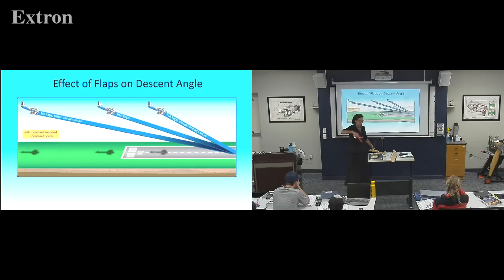You have the flaps helping slow you down, so you can clear obstacles as necessary. So this is a no flaps approach, which I do into Ionia, especially if it's windy. But we have a super flat descent angle. And then half flaps, full flaps, you can just dump that in over the trees and land.